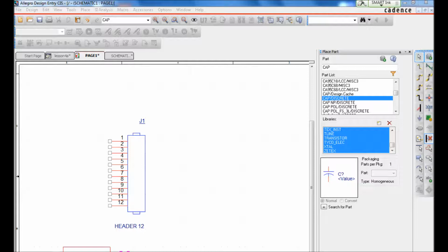Alright, so resuming here, we had a little issue with the net alias, but we fixed that. As you can see, I have C1, C2. You can always alias a name for your reference designator by just pressing the N on your keyboard. So I'm going to go ahead and save.